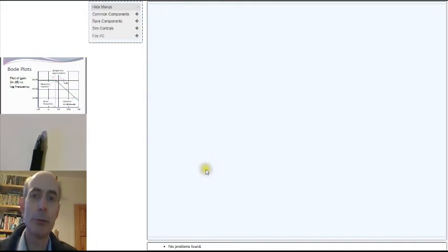The first thing we'll have to do is build an op-amp amplifier. A non-inverting op-amp amplifier is the first one in the lab. This will require getting a split rail power supply, so plus 12 and minus 12 volts from the lab power supply unit. If you're not sure how to do this, there's a document about it on the lab webpage. Have a look at that one first. There are a few traps for the unwary.